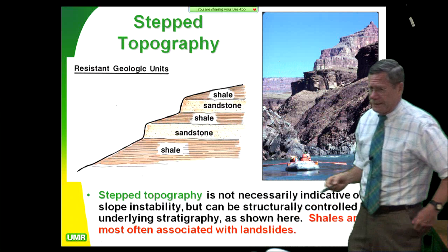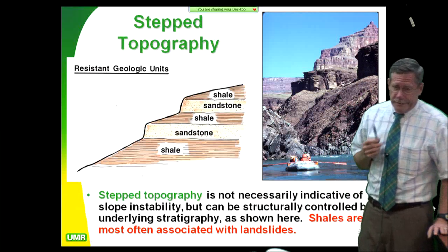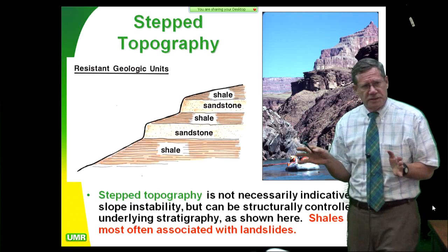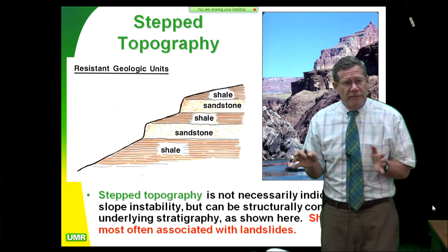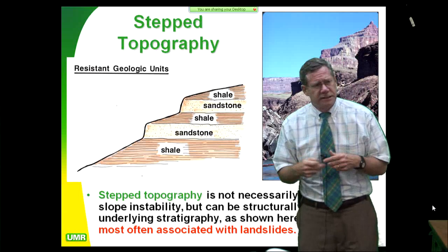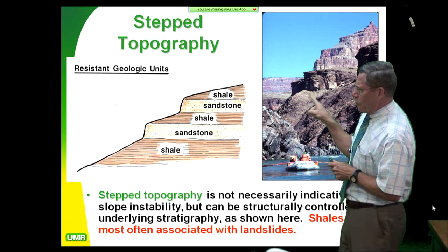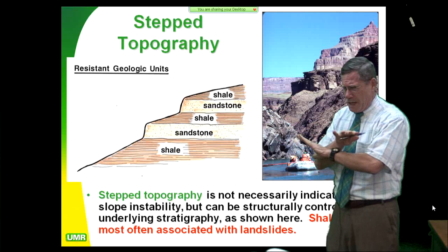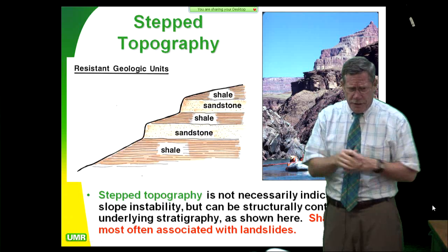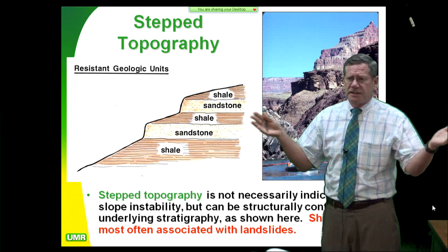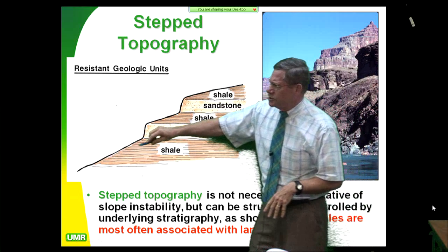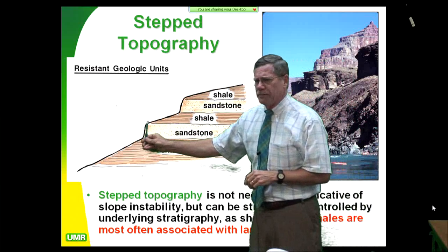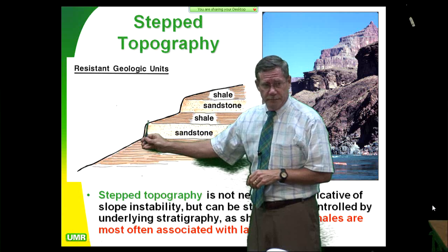Now, you go out to California, where they got people with too much college training, and they've run around the whole place and classified slopes, and they do something called slope density. And they reason, without talking to people like us, they say, well, the steeper slopes are more dangerous. More dangerous, more prone to landslides. So if it's a steeper slope, we're going to make it red and tell you you can't build there. Now, the reality is just the opposite. The flatter slopes and the shales are the huge landslides. The steeper slopes are the more competent materials, which you'd be better off building on, but cost a lot of money to build on.